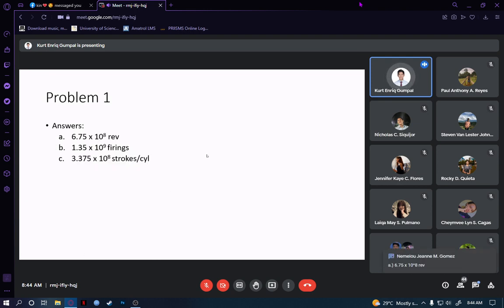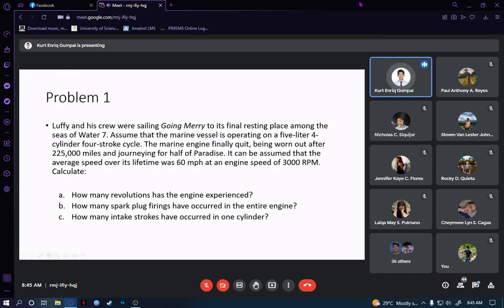Your A is 6.75 times 10 to the power of 8 revolutions. Okay. Your B is 1.35 times 10 to the power of 9 firings. And then your C is 3.375 times 10 to the power of 8 strokes per cylinder. Okay? How did we get it? Your 225,000 miles, you multiply it with your 3,000 RPM. Now, you convert it to per hour, you multiply it by 60. Divided by your 60 miles per hour. Okay? That becomes your 6.75 times 10 to the power of 8 revolutions.